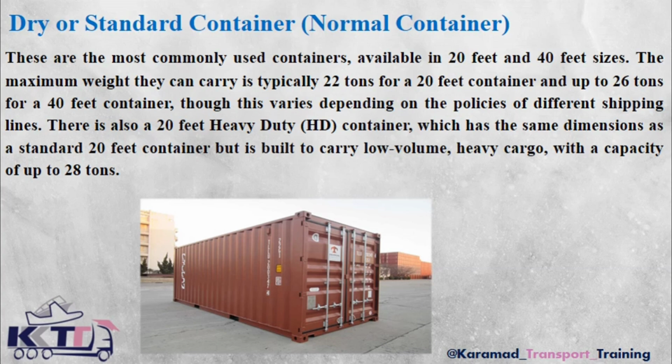Of course, this weight also depends on the loading policy of the shipping company that owns these containers. It also depends on the weight indicated on the CSC plate of the container, which I covered in the previous lesson. I mentioned that it's very important for us to check what number is shown on the CSC plate for the gross weight because we are only allowed to load the container up to that limit.